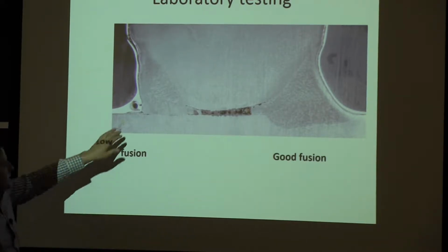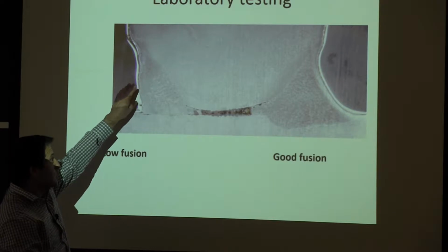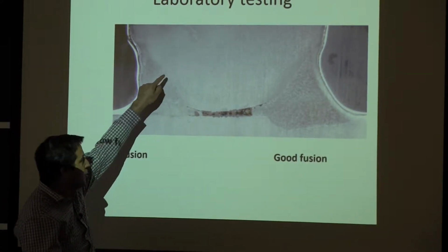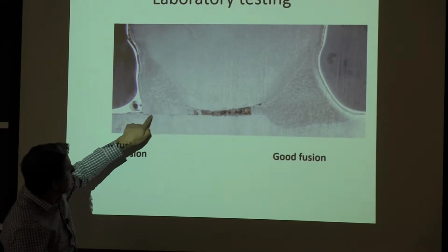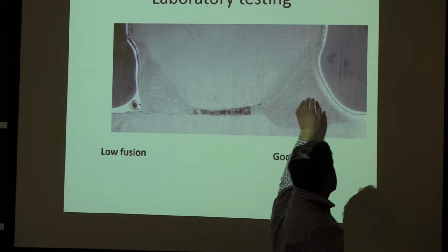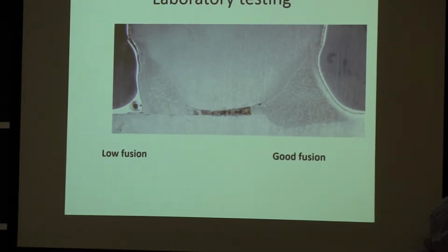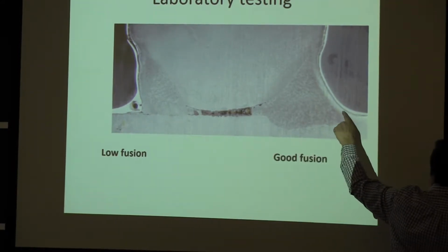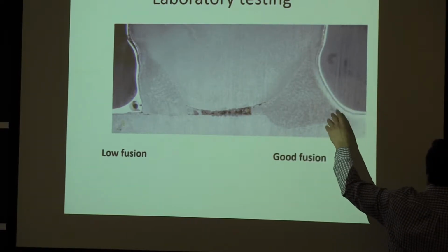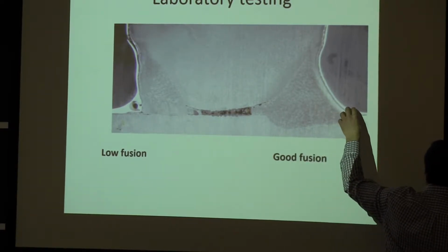And this was an example that didn't work so well because they put all the heat to melt the bar, which is the hardest component to melt, but there's really no significant fusion on the tube over here. And that was an example that was better done. And I mentioned the surface tension equilibrium here. So when it looks really smooth, it's because you had enough heat, you had the fusion.